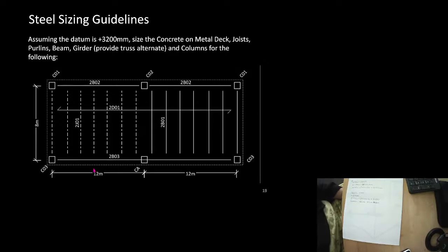Does that have an impact on it? Knowing very early that you've lost that 400 millimeters from what you might have estimated by designing it as a beam is really important. That could have an impact in a very preliminary stage. And remember, this would be before you've hired an engineer. So these are big structural implications that you're making before you even hired an engineer. So the last thing is, let's size the columns.